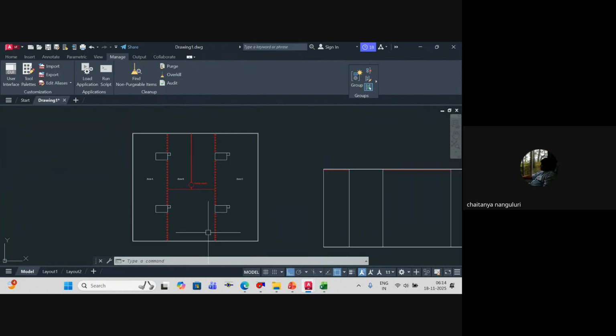So shall we proceed further? Sir, here can we eliminate the sprinkler system, or do we have to consider it? Yes, sprinkler is different. Water curtain is different. If you do not have sprinklers, each area should not exceed 3,000 square meters, so your density will increase a lot. Along with sprinklers, parallelly you should have this.